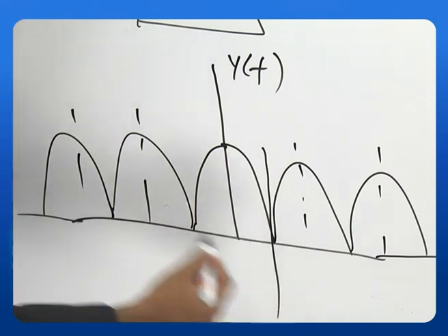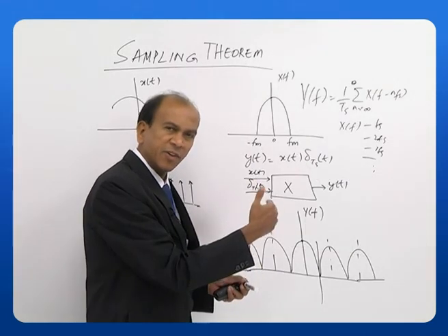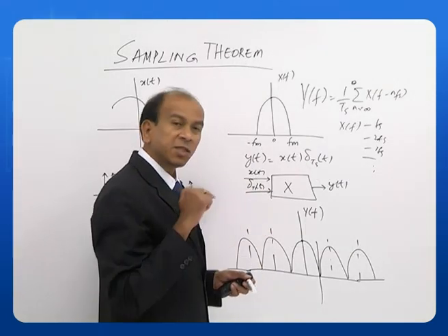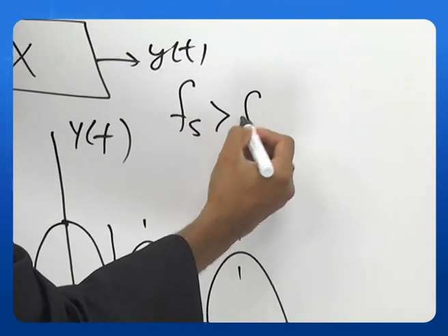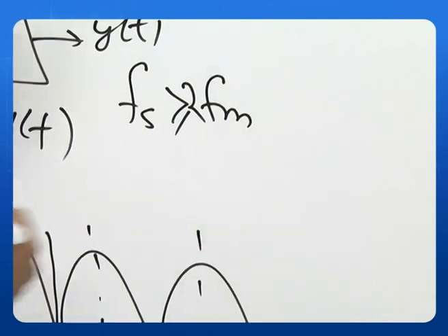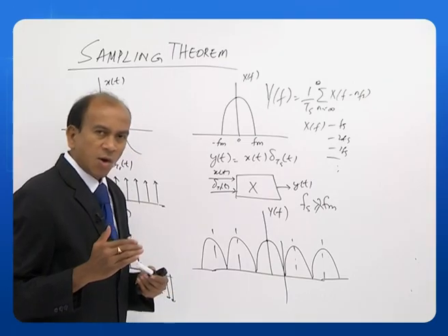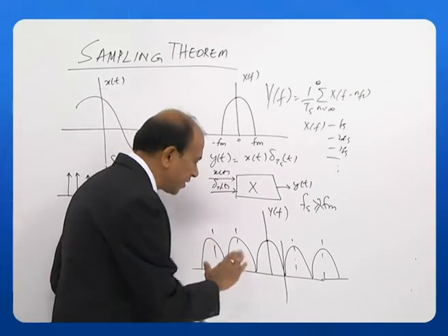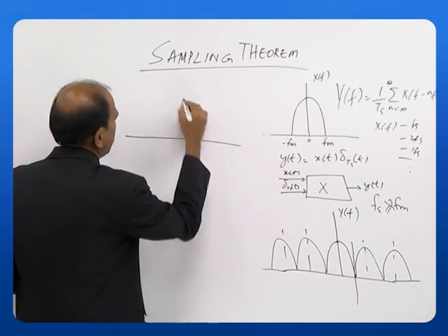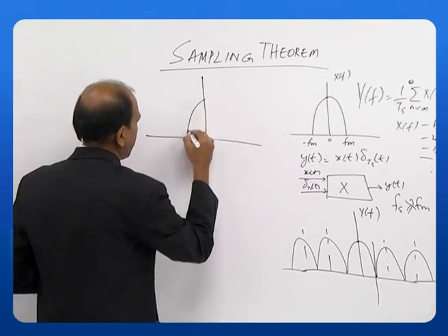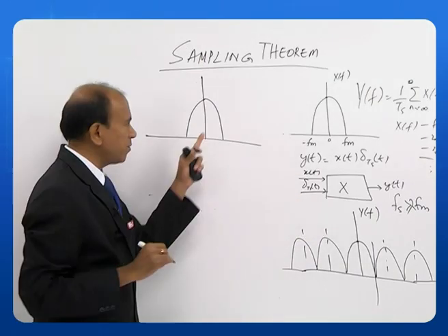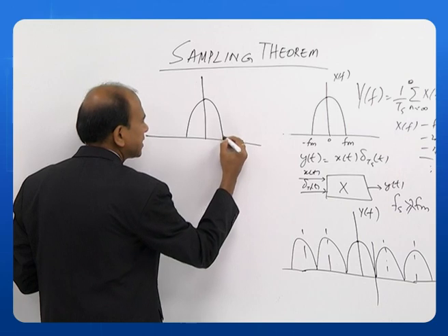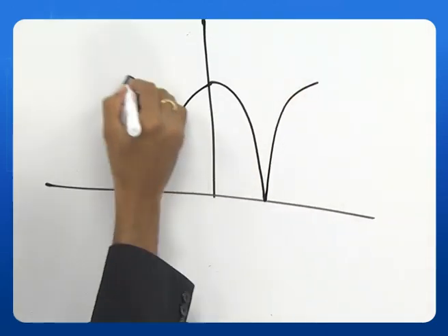So, here the first one is ending and immediately the second frequency is repeating. This is possible because we have taken the sampling frequency as greater than 2Fm, Fs greater than 2Fm. Once this condition is satisfied, there is no overlapping. That means, if you look at this here, Fs greater than 2Fm, you have this, and then the second one is starting exactly where this is finished.